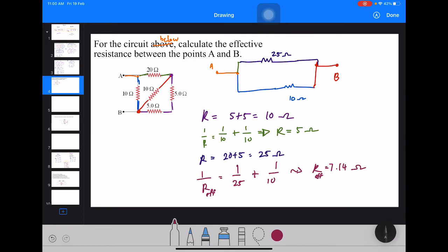If I'm familiar with the one where the resistors are lined up along the x-axis, that's the one I usually draw. If you're used to drawing like that, do it like that. And then if there is a positive power supply, usually I put it at the bottom or at the top. If I draw it like that, I can see clearly whether they are in series or parallel with each other. It takes a bit of time, but like I said, I really spend time and my answer is correct, so that I can get full marks, because this is the first step to find the R effective.